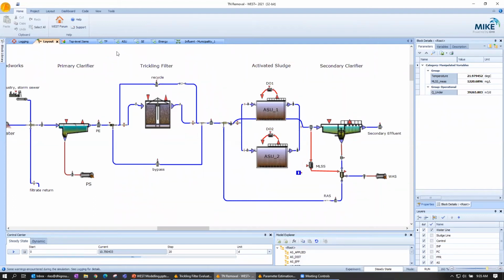But the other conclusion that was a bit more surprising was that these trickling filters, if they're near end of life, it might not make sense to put $20 million into the maintenance of these things. If they need full new media beds and they need the concrete or the tanks themselves reinforced, we need to reconsider that allocation, because that's a lot of ratepayer funding that we can allocate towards longevity of this plant and moving towards a denitrifying process.